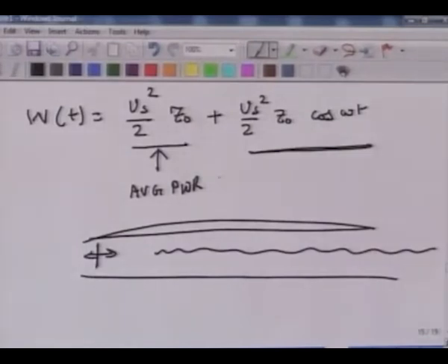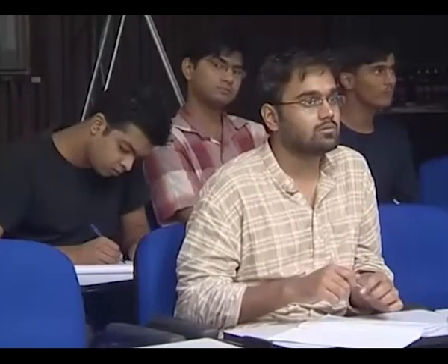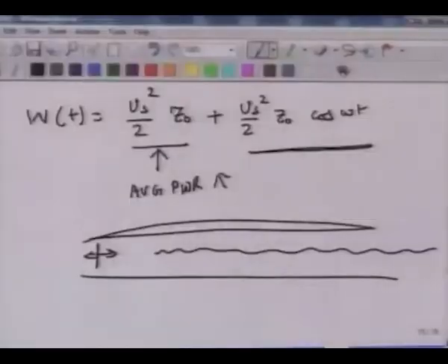So my average power consumption is non-zero. So physically also it makes sense, even though in both situations you don't have any damping happening. Please explain this once more, the physical interpretation in a closed tube and an open tube. So if you have an infinitely long tube, you have a membrane in an infinitely long tube and it's exciting air.